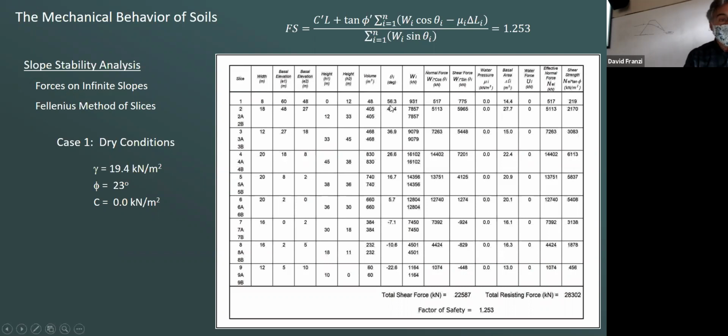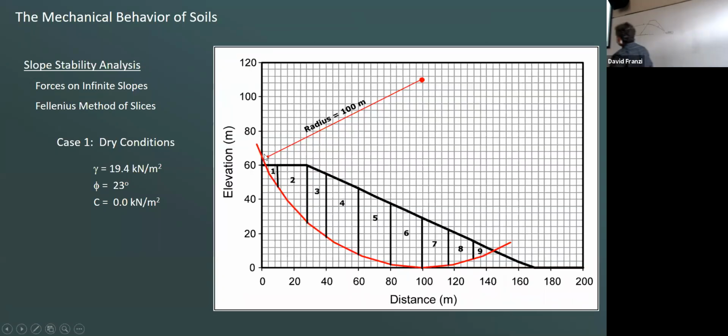The slope angle, well, all you need to do here, there can be a pretty steep slope here for the first leg, but you can just take the x and the y dimensions, so you can use some trig to calculate what the slope angle is. That would be the opposite side over the adjacent side, so you're going to use the tangent to get that. And then you can calculate the length of that, the hypotenuse, the length of that slice. That's your actual failure surface.